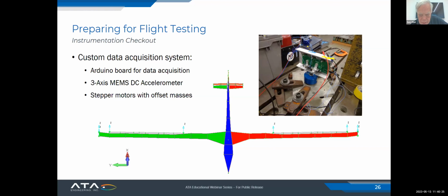That's standard practice for aeroelasticity tests. You do not want the excitation from the aerodynamics when you're approaching the critical speeds. So you want to excite the mode and the frequency as you approach the speed, and you see how the damping is coming out, and where you have to stop.